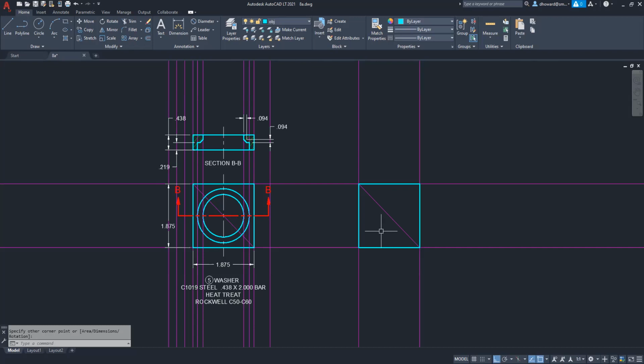and then the circles themselves that are the hole and step through this washer. The hole itself that goes through this washer is just slightly larger than the post. Remember that the post diameter was 1 and 7/32. That's going to go through this thing. So it's just, I believe, another 32nd. So 1 and 8/32, right? Which works out to be 1 1/4 inches. So the diameter on that is 1.25.